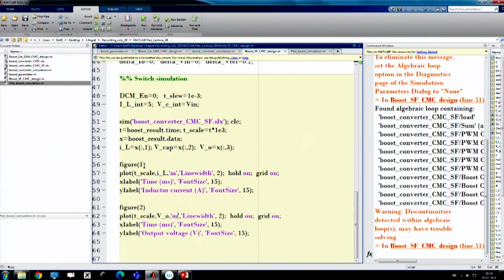Okay. So, let us wait, because we set here again 1/3, so they are the same, like 1/3 here, in both cases the crossover frequency is set to 1/3. So, I have designed by means of pole placement and then it will give the value, where in output feedback we set 1/3 of RHP zero crossover frequency, here also we set 1/3 of the RHP zero, and let us see what happened in the response of the converter.